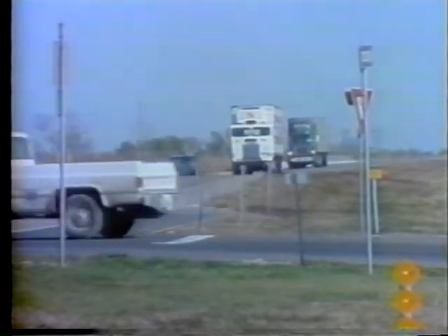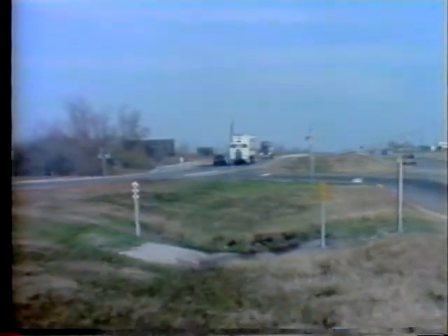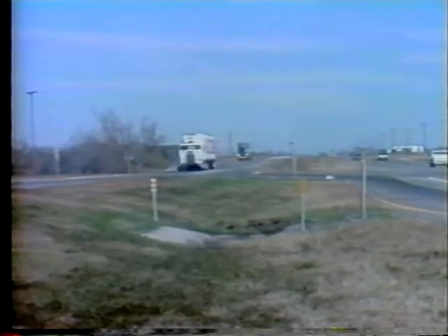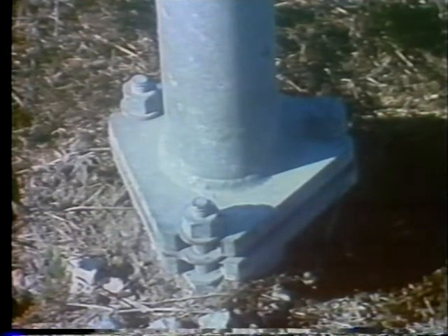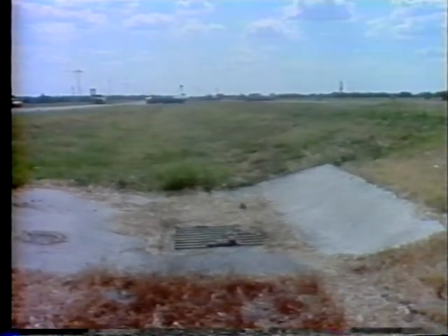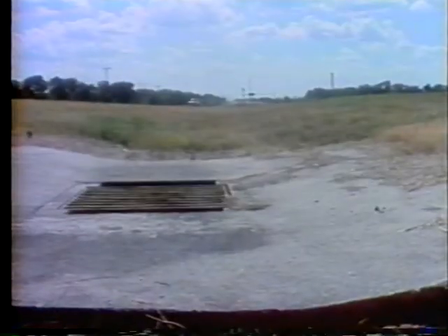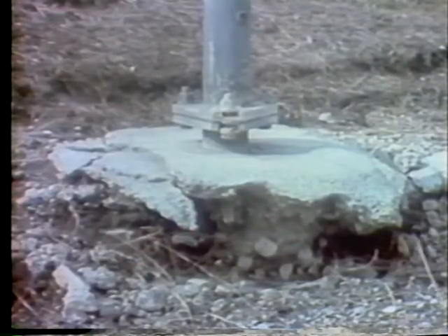The flattening of the slope is not the only factor that must be taken into account to make a side slope safe and traversable. Another important factor is keeping the slope free of fixed objects. Sign and luminaire breakaway bases and drainage structure elements should be constructed flush with the ground line so that an out-of-control vehicle can easily traverse the slope and not snag on these devices.